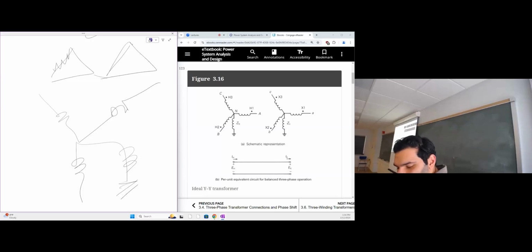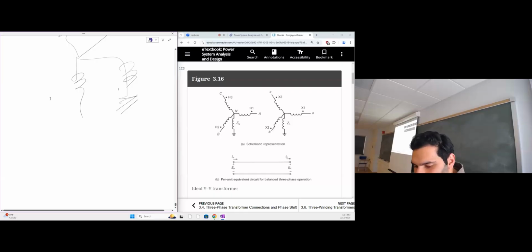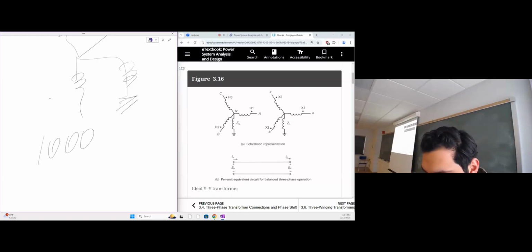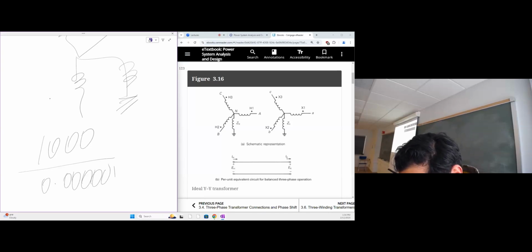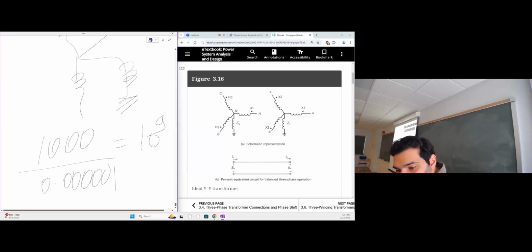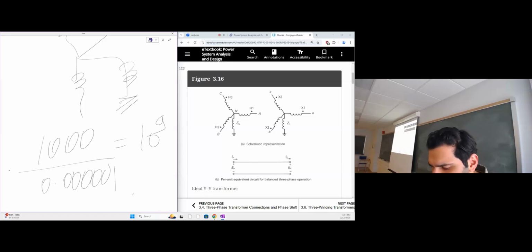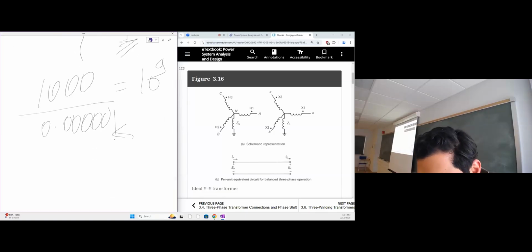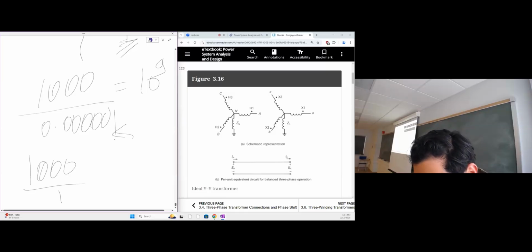So in case you had a 1,000-volt strike and you had the impedance here almost nothing, it's not zero, but 0.something, the current that will be circulating will be on the order of 10 to the power 9. It'll be a huge current. Even with the grounding, it'll be huge. But if I put an impedance of just 1 ohm here, I'll be still getting rid of that extra current. 1 ohm only.